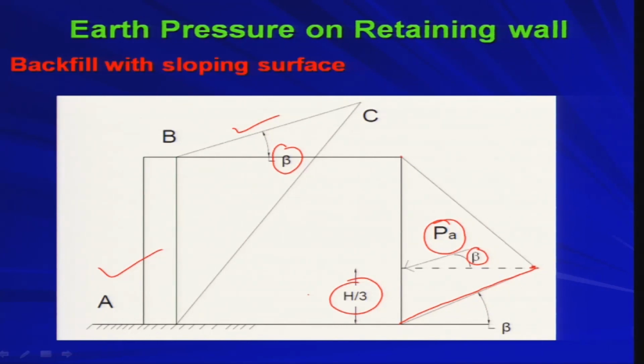Okay. So, now basically so far what we have seen, whatever active earth pressure coefficient or passive earth pressure coefficient we have calculated, those are based on Rankine's analysis. So, Rankine did not consider the friction of the wall. That means, he considered the wall is very smooth and there is no friction between wall and soil, right. So, suppose this is my backfill, okay, and this is my wall. If I want to separate it out, this is the wall, say. So, I do not have any interface friction, okay, at the backfill and wall interface. So, that smooth condition or frictionless condition was considered by Rankine.